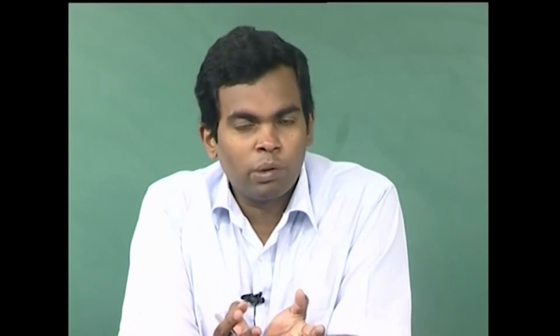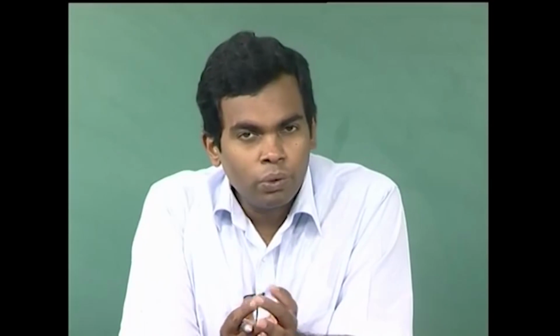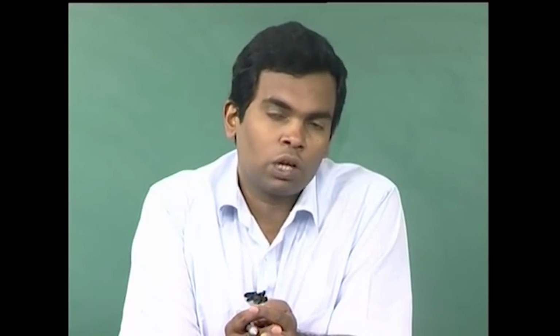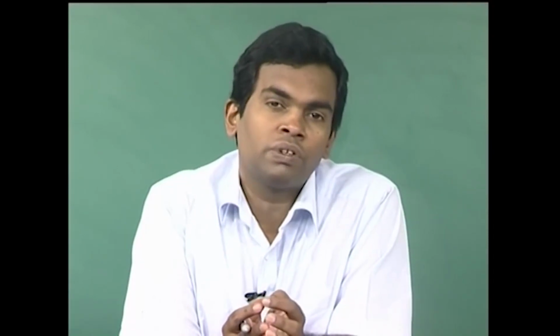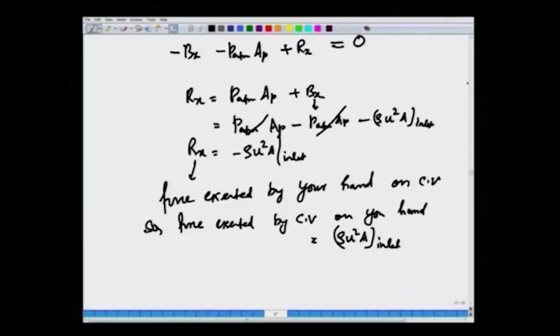Clearly the CV is actually our construction. The problem does not care for CV. The actual physical processes do not care for CVs, whereas if you want to analyze it, you choose a CV of your convenience, but the answer should come out to be the same regardless of the way in which the CV is chosen, so long as all the steps are done correctly. So, that is the key thing that we have to remember when we do momentum balance.